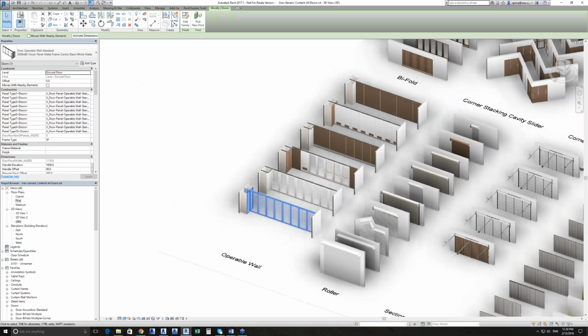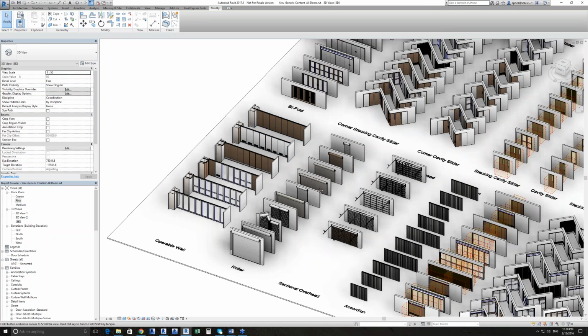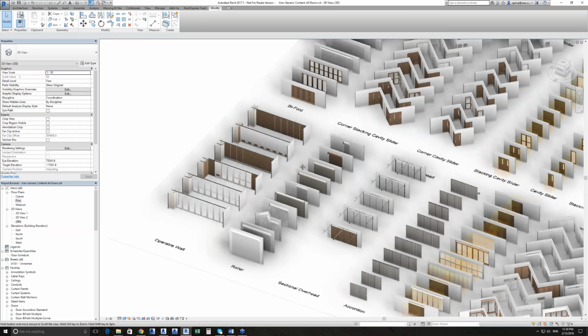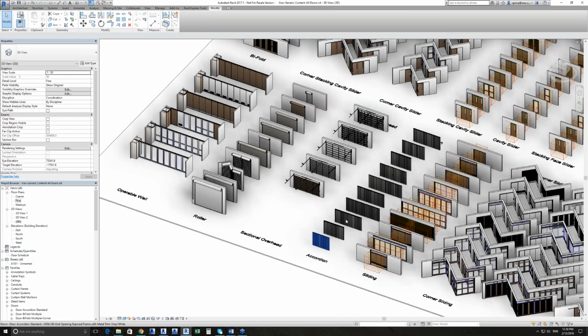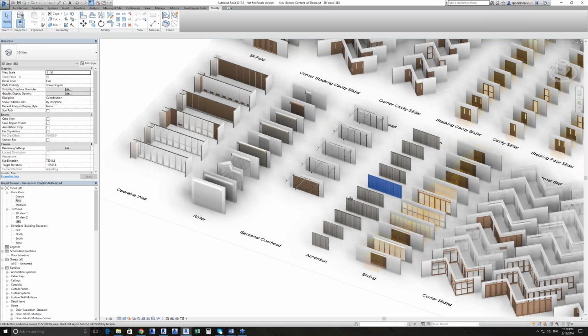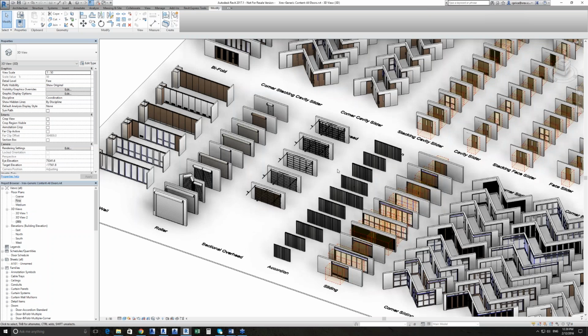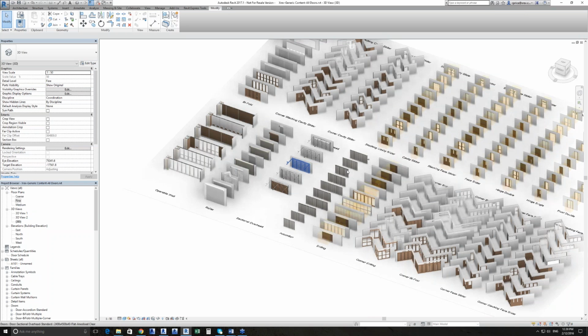And just quickly as well, with things like the operable walls, they operate as standalone families. They're actually not hosted by a wall itself. That's because they are typically floor to ceiling. And likewise with the accordion doors, you can see there's no wall there because they're a room separation device. So those ones have deliberately been created as unhosted, just because there's issues in Revit if you go and place a wall and then put a door in it that occupies the entire extent of that wall and then try and copy it somewhere, or if it's in a group or something like that, you'll get issues because the wall that's hosting the door doesn't get copied and Revit can't create the door. So we've thought about all those types of issues that you might come across. But they're still placed using the door tool and scheduled as a door. Correct, yes.